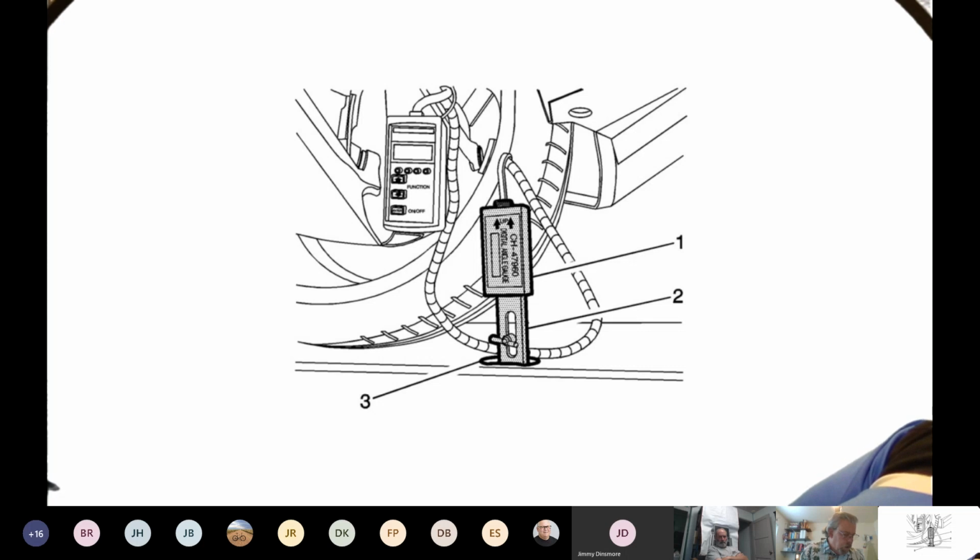Rear caster had a big effect on suspension loading when they would start putting lots of power to these cars. How I got involved is he worked in a shop that did a lot of modifications. So they were supercharging, turbocharging, all these things to these Corvettes. And they'd get into a lot of squat, and then the cars would start going all over the place because a lot of it led to the rear caster problem, and then it would also affect camber and toe.